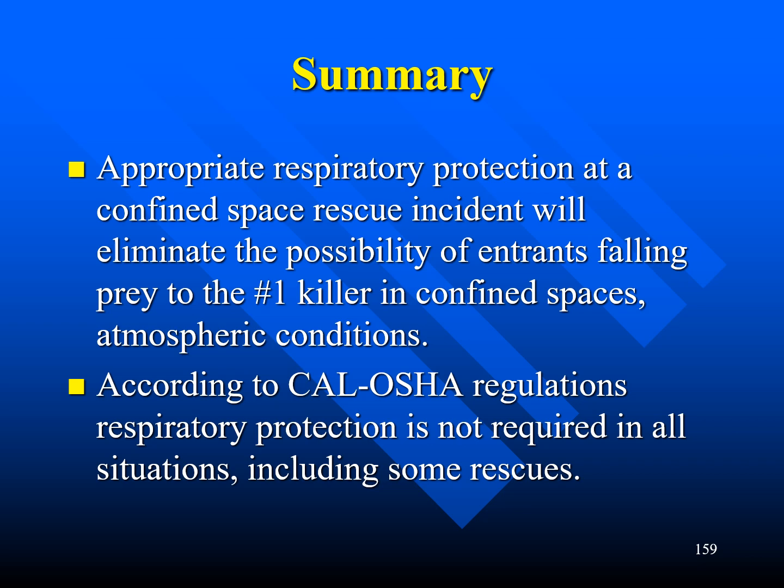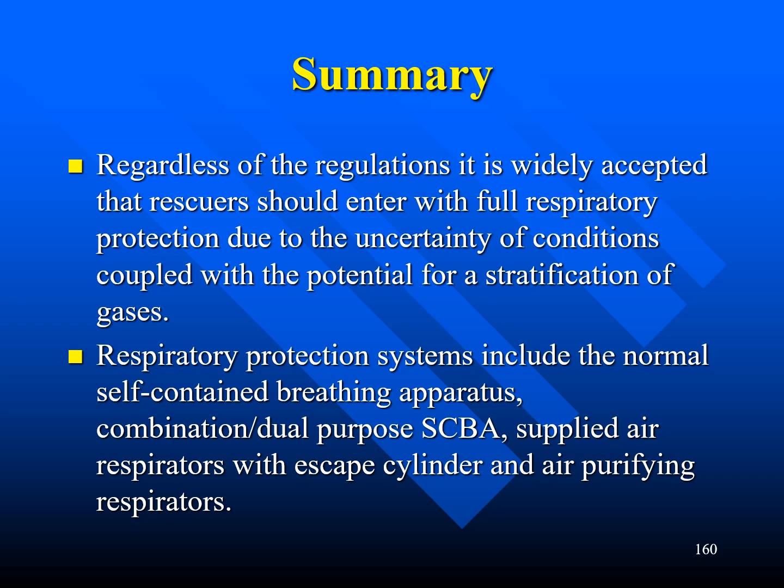Let's summarize this lesson. Appropriate respiratory protection at a confined space rescue incident will eliminate the possibility of entrants falling prey to the number one killer in confined spaces, atmospheric conditions. According to Cal OSHA regulations, respiratory protection is not required in all situations, including some rescues. Regardless of the regulations, it is widely accepted that rescuers should enter with full respiratory protection due to the uncertainty of conditions coupled with the potential for a stratification of gases.